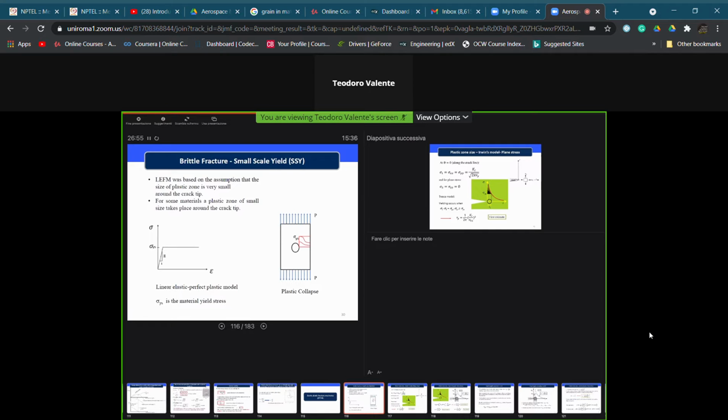That is a relationship between the stresses and the strain in the material, for which we do have the Hooke law, a linear perfect elastic behavior, till we reach the material yield strength, or yield stress, obviously it's the same in this case. And then we do have stresses which are blocked with an increase in strain till we have a complete plasticization of all our material.